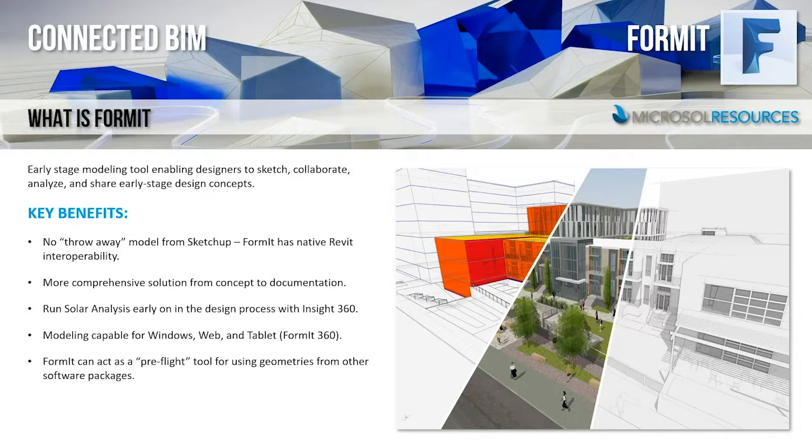By uploading your Format model to the cloud, you can access and present your models anywhere on multiple devices through Format 360. Format can also act as a pre-flight tool where you can bring in geometries from other applications such as SketchUp or Entourage by using plugins in Format to validate and clean the elements from other resources that may have invalid geometries. All this then allows us to bring this information into Revit through the use of import tools built into the Revit platform that we'll look at here in a little bit.